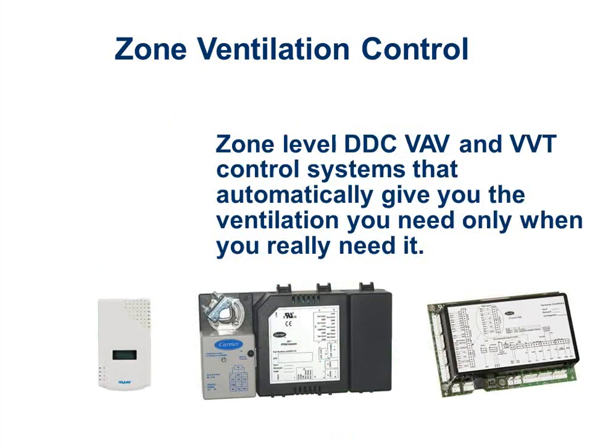All right, so what does it take to do one of these systems? On some equipment, it's extremely easy, such as a packaged rooftop unit. Packaged rooftop units, in almost all cases, have an economizer on them. New ones certainly do, because economizers are required by code in most states down to 5 tons. In some states like Illinois, down to 2 3/4 tons. So usually you've got economizers on stuff that's been put in the past 5-6 years. But even before that, older equipment on larger units probably had an economizer for energy reasons.